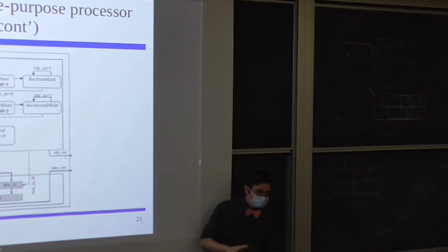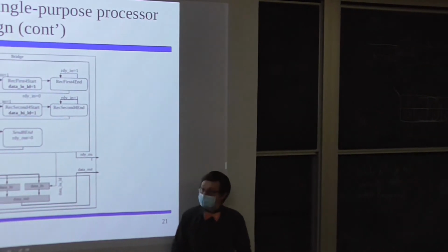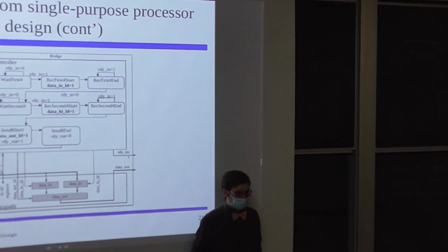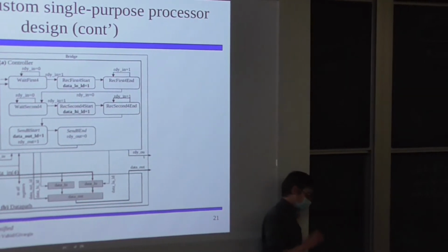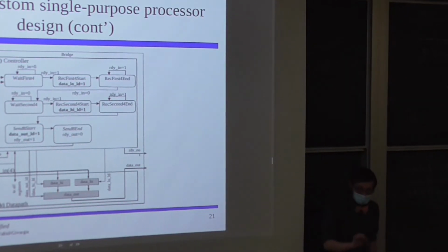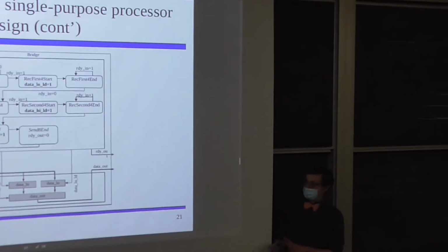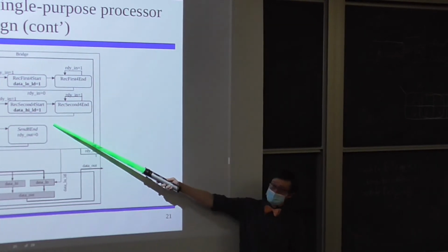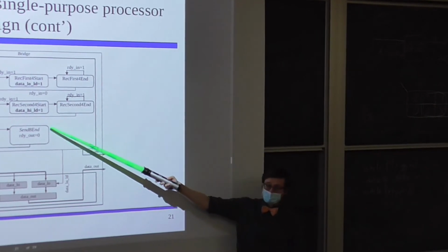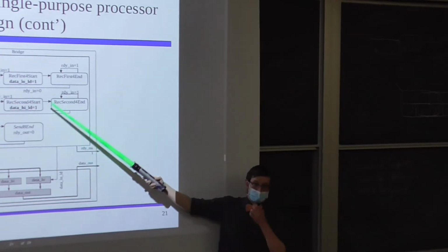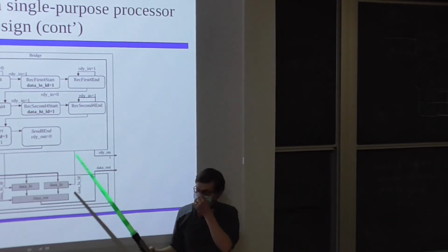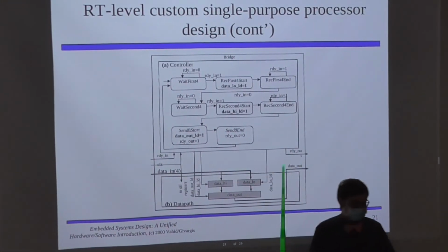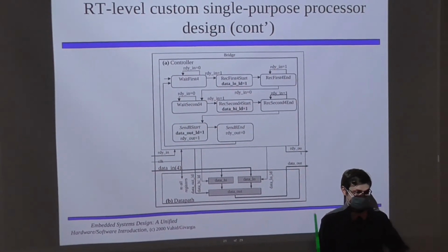While we are only performing 3 assignment operations here, we are passing through a number of different program states because a lot of them are just waiting for the ready signal to go high or go low again, right? So those waiting states, while they are not actively pushing values to signals in the data path module, are still perfectly valid states. Some of these states are redundant, we don't need all of them, but what we've done over there on the chart is a faithful recreation of this algorithm as designed.